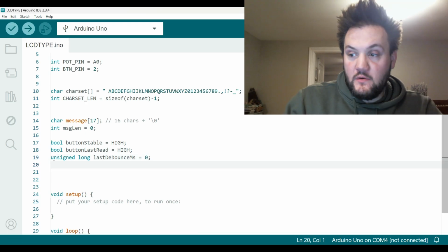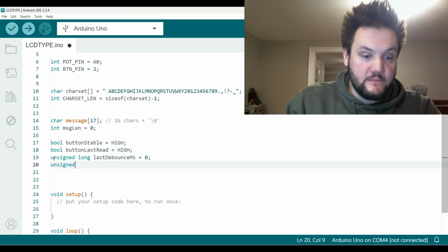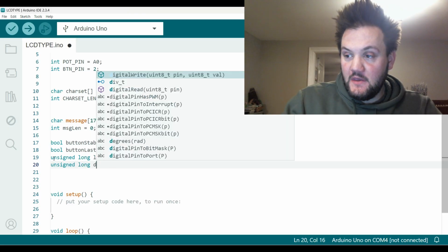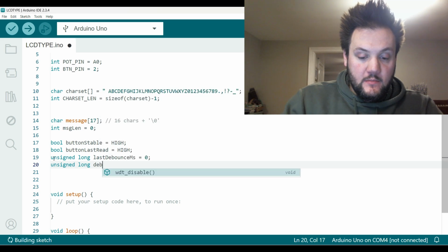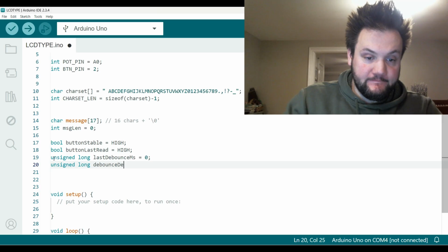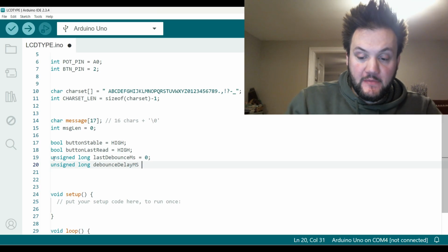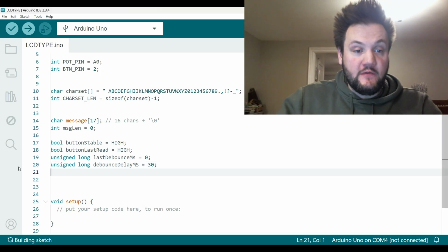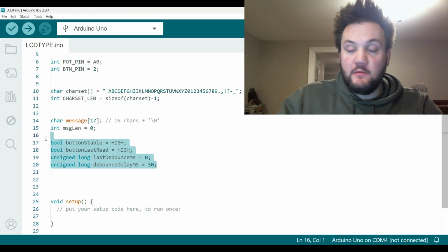And then we're going to go another unsigned long. We're going to set this equal to the debounceDelayMS. And we'll set that to 30 milliseconds. And we're pretty much there and done for the establishment of these items that we'll use for the debounce.